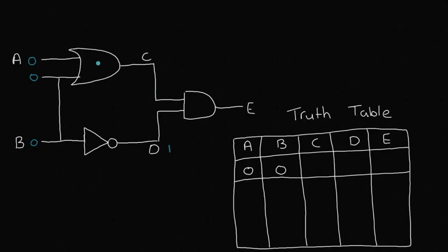And our OR gate here will be true, or will be 1, if 1 or more of the values are 1. Now unfortunately for this example, both of our input values here are 0, so 0 and 0 still gives us our output as 0 or false. So I'm going to put down 0 beside C because that's the value for C. Now moving on to this next step, you can actually bring this 0 down here if it makes it a little bit more readable for you, and we can bring this 1 here.